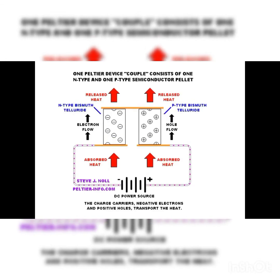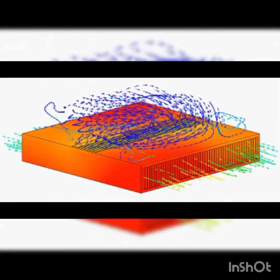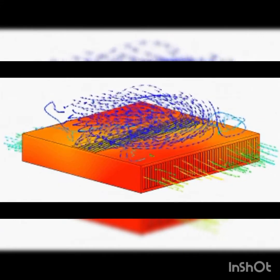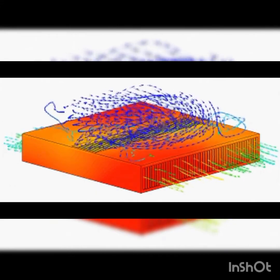Applications of the Peltier effect. Peltier elements are commonly used in consumer products. They're used in cooling electronic components and small instruments. The cooling effect of Peltier heat pumps can be used to extract water from the air in dehumidifiers. The Peltier effect can be used to create a refrigerator that is compact and has no circulating fluid or moving parts. Thermoelectric coolers can be used to cool computer components to keep temperatures within design limits or to maintain stable functioning. A Peltier cooler with a heatsink or water block can cool a chip to well below ambient temperature.